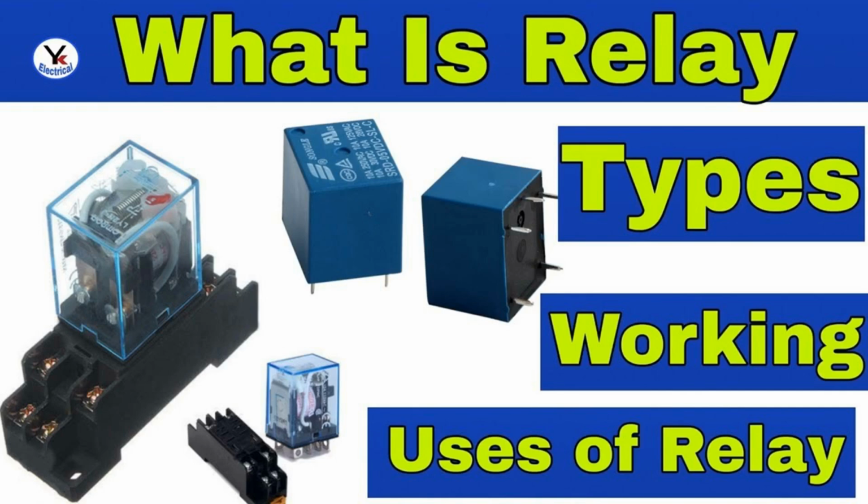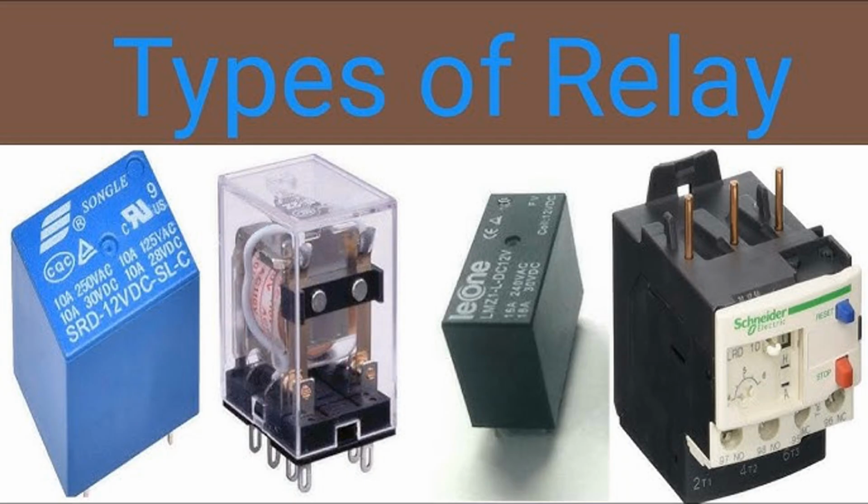Applications. Lighting control systems. Used to control lights with a single push button that alternates the lights between on and off states with each press. Memory retention circuits. Ideal for circuits that need to maintain state during power outages, such as alarms or emergency systems. Automotive applications. Used in cars to keep circuits on or off without continuous power, like in central locking or power window controls. Industrial and building automation. Controls for HVAC systems, alarms, and motorized gates where maintaining the last state after power failure is essential.